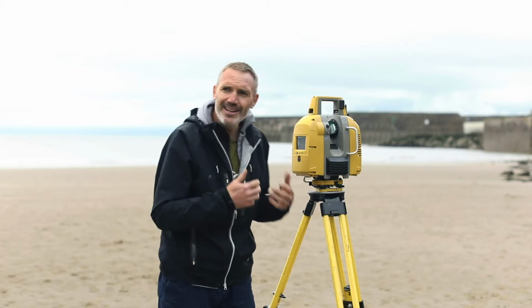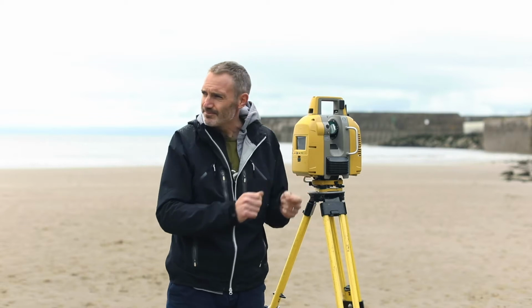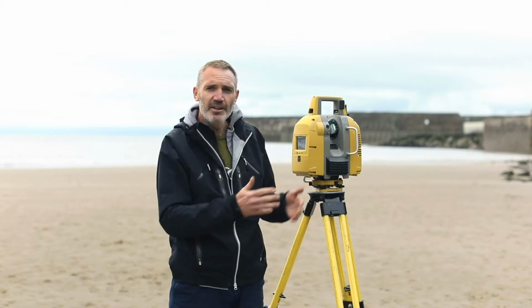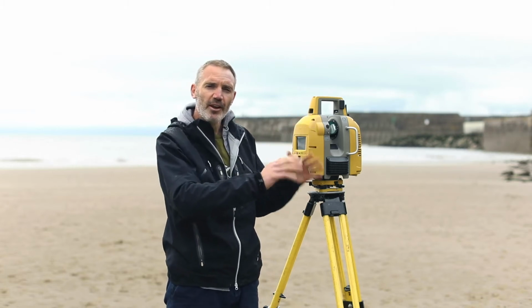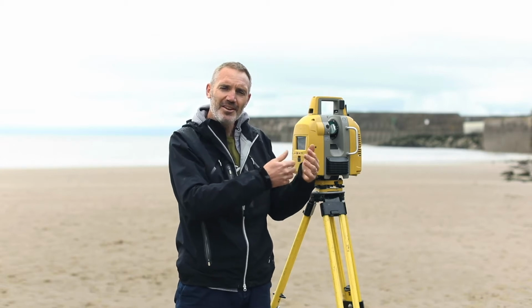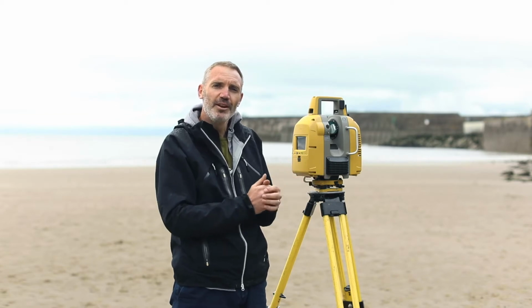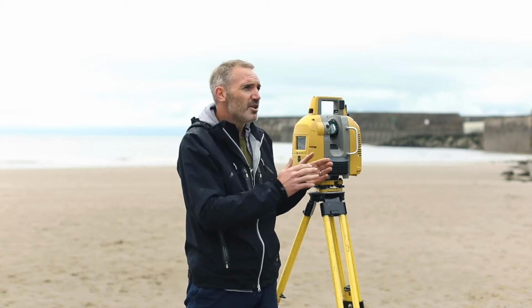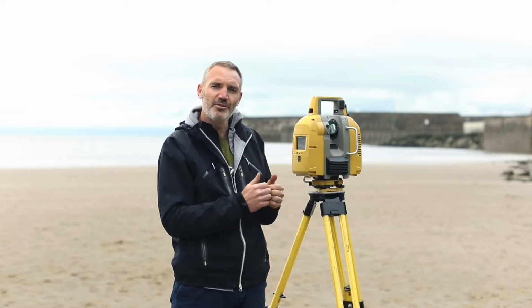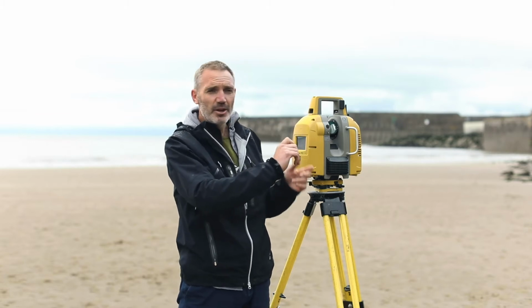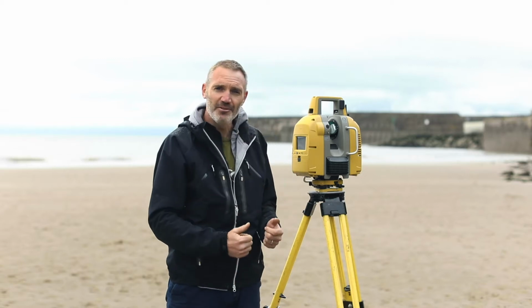And the beauty of this technique is that because we've got this mass data capture and that sort of accuracy, it means that we could come back here in a year's time, maybe after a season of winter storms, and measure the same surface, and then compare the two. We can see areas that may have moved, even individual blocks that have been forced out or moved in the wall. That gives us a much greater insight into how this structure is actually behaving and reacting to those forces of nature than if we were just measuring discrete points at, say, 10 or 20 or 50 meters using conventional survey techniques.